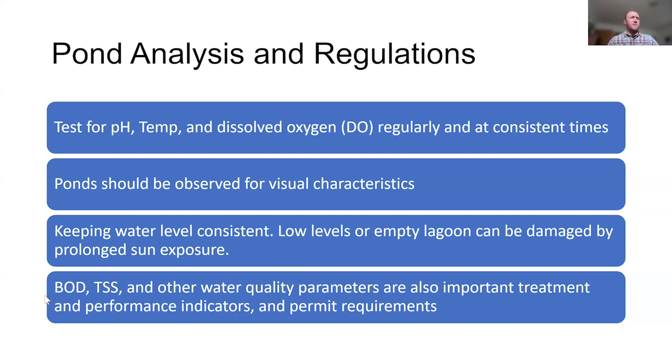And then it's also good to monitor BOD, TSS, and other water quality parameters, whether it's flowing in or flowing out, so you can see your percent removal. That really serves as an indicator of how well your lagoon is functioning. And also for your permits, of course, you have to measure those.